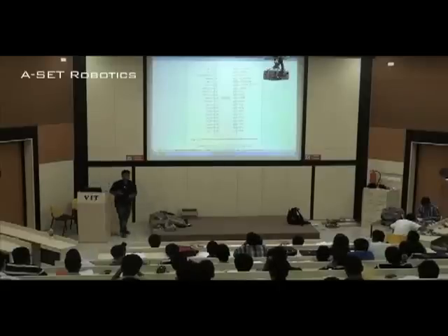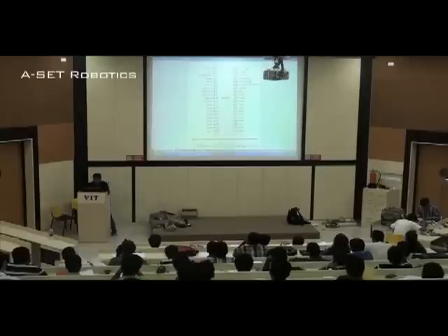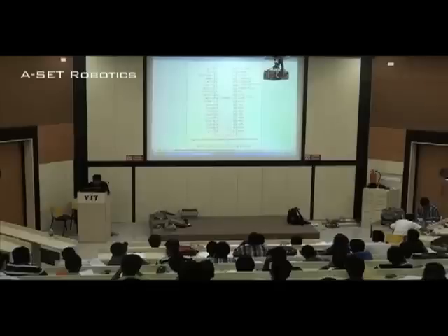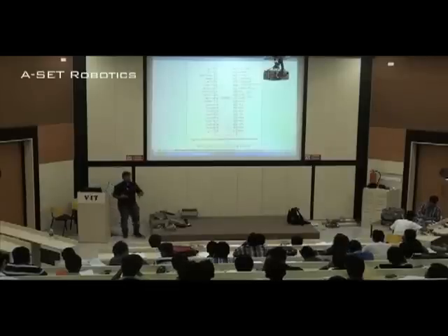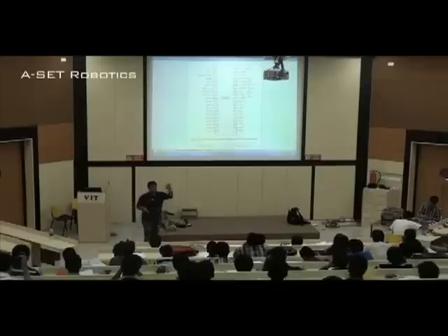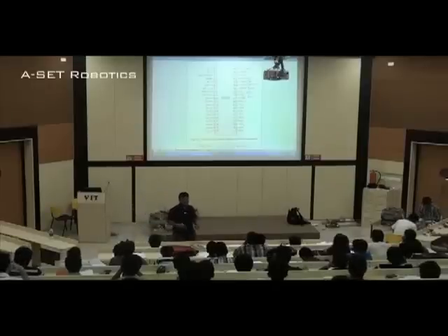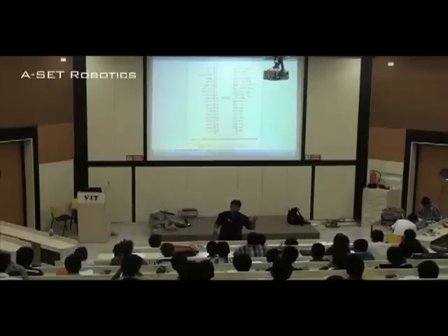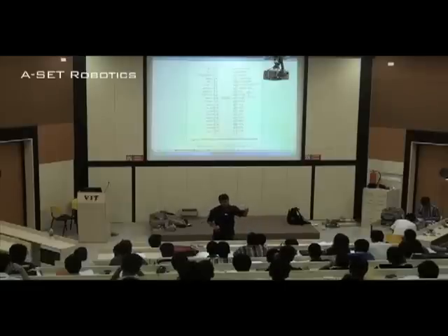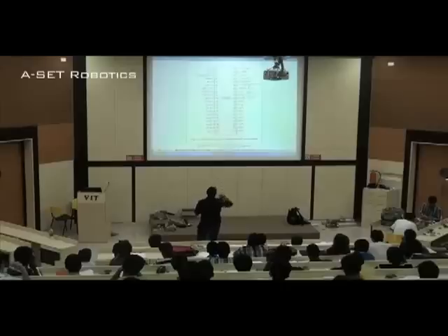Now what happens is, before doing the ready signal, let's concentrate on IOM. That is more important. IOM and read and write. Whenever the microprocessor puts an address on the bus, it has to indicate whether it has to read or write. And how will it indicate? It will indicate by these 2 pins.